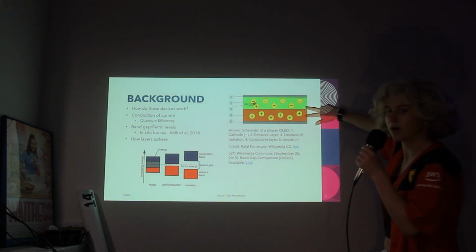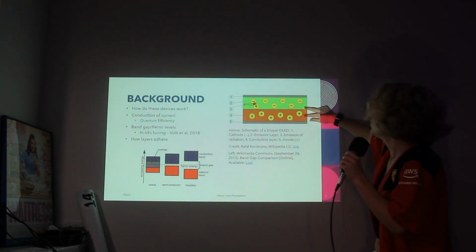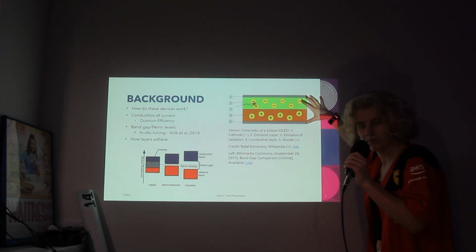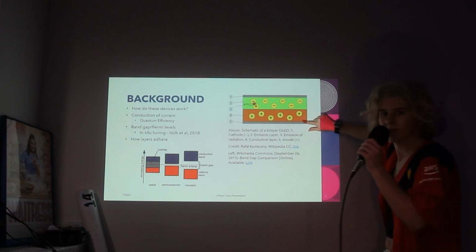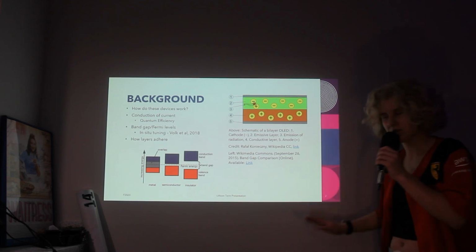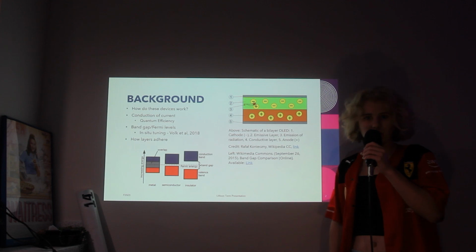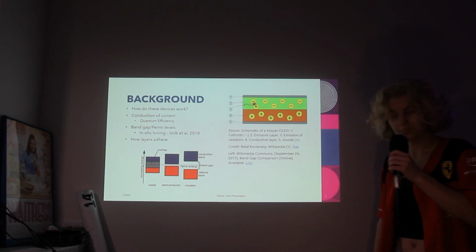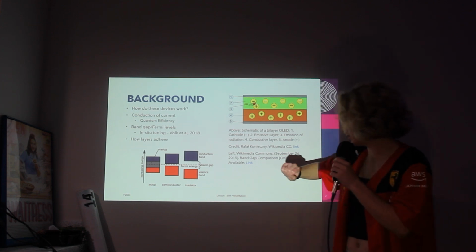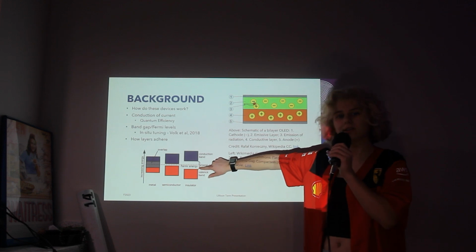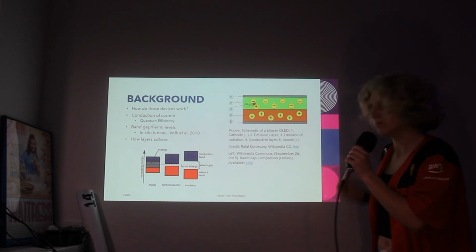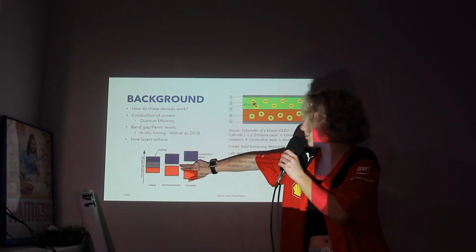Now, these two layers are oftentimes organic materials, and then the anode and the cathode are metal, which is why this interface here has some issues, because organic materials don't like binding to metal very well without change. So organic semiconductors aren't very good at being semiconductors without some modifications to the band gap, because organic materials have a big band gap, as you can see here. Without modification, organic semiconductors act like insulators, but with modification, they will act like a semiconductor and the bands will be closer.